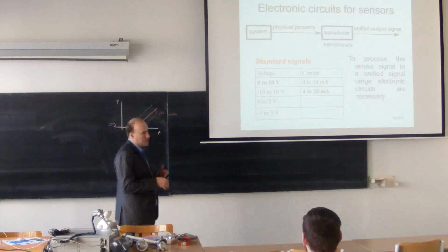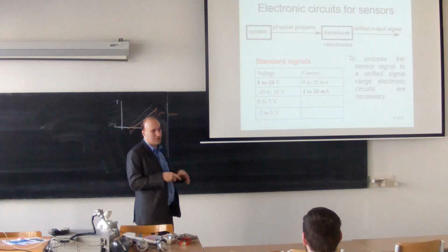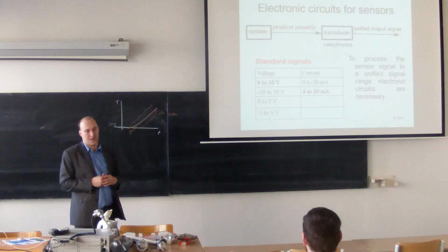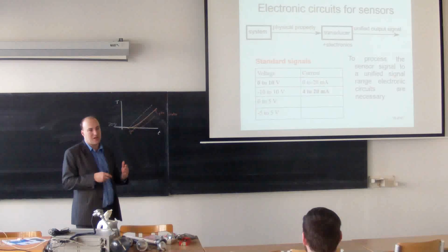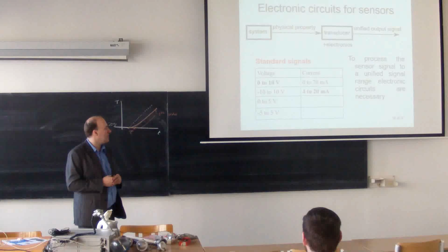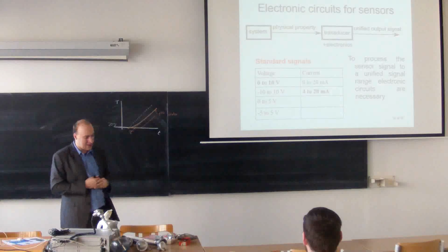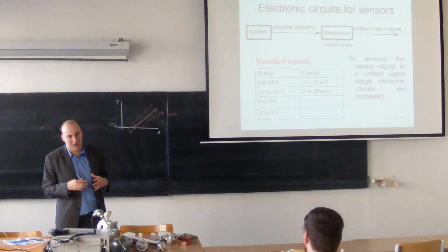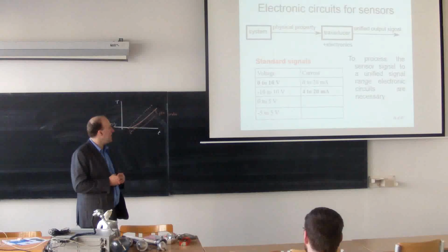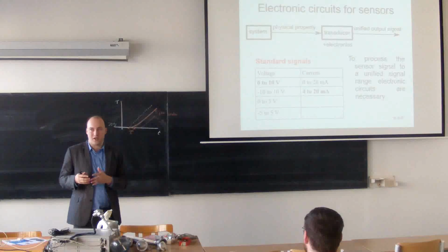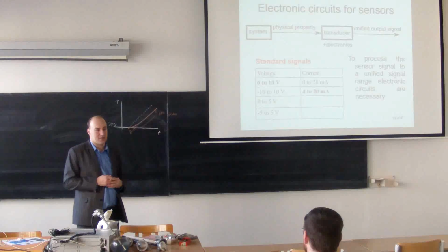So we'll need some circuit that takes the value from the sensor and transfers this to some standard signal. It can be temperature, it can be pressure, it can be humidity, whatever you can imagine. The reason why we do this is that I want some standard control system and I want to connect this with some other manufacturer that is doing the sensor.